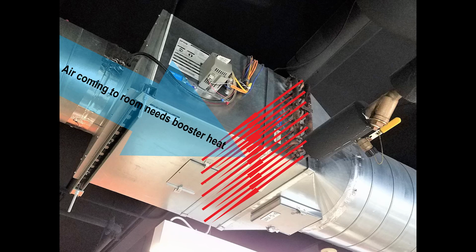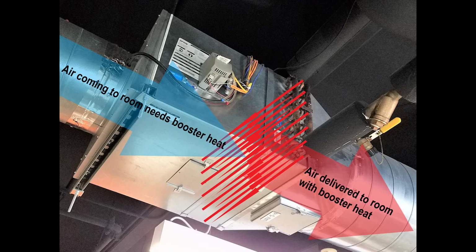Air from the building or bulk air supply that isn't quite warm enough is blown or forced through the booster coil in the VAV box. The booster coil provides additional heat to the air moving through it. That extra heated air then enters the room or building space that needed the extra heat.